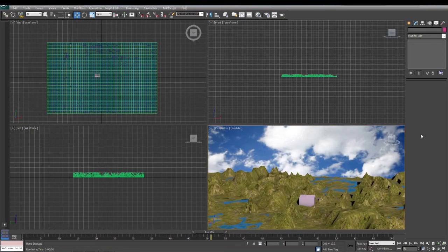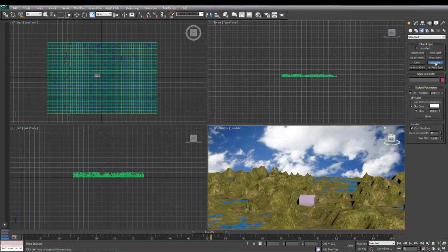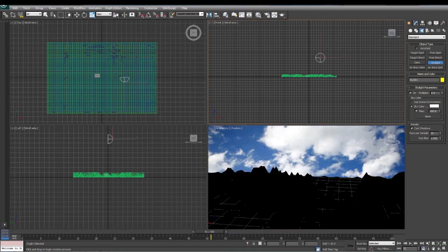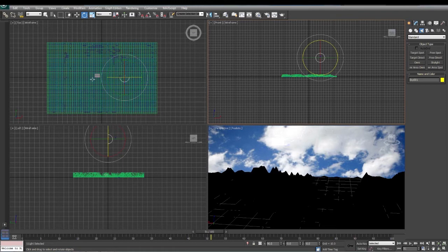One last light we're going to look at is a very useful light if you don't want to get into all of the daylight system, setting up the times and doing animation with that kind of thing. The Skylight. When you click on it and I click, you're going to notice some things change automatically here. Everything gets dark. I'm going to rotate my Skylight down. Right now it's at a flat part here and it's rounded. I like to have the rounded part down, signifying the light direction, a little bit of an angle.